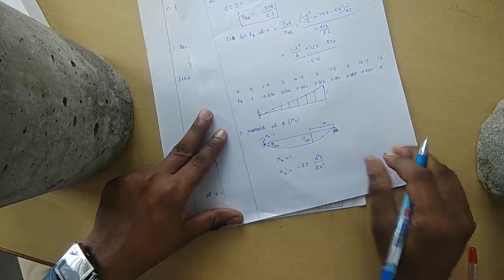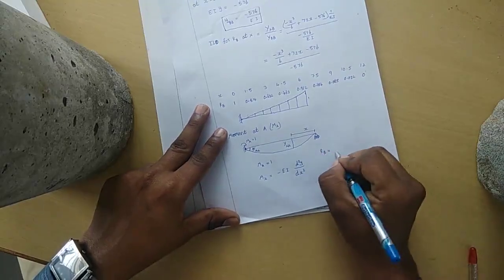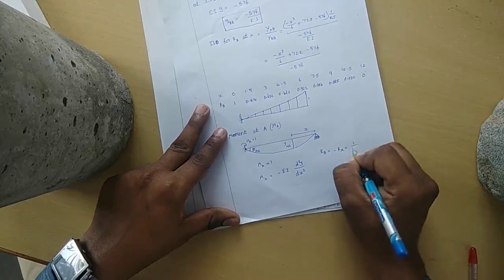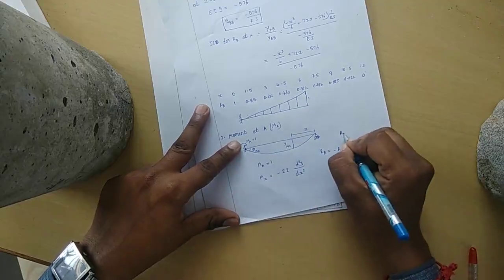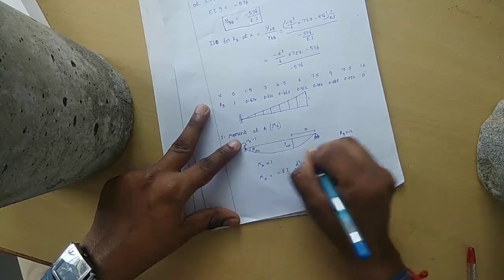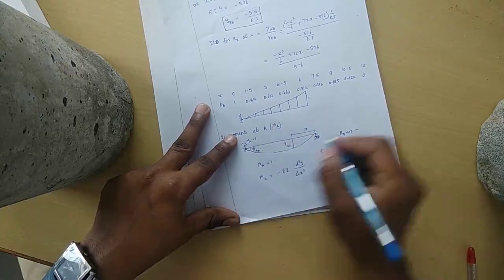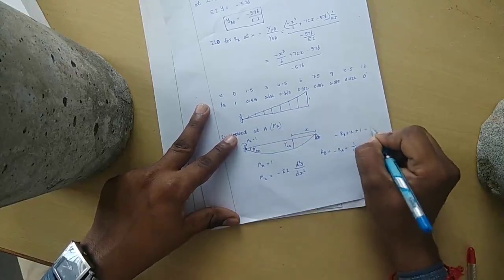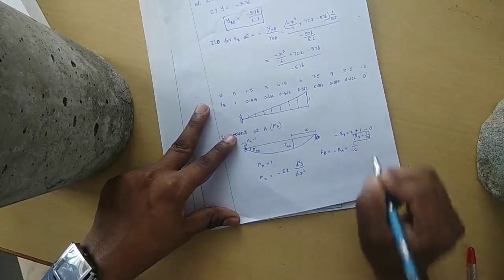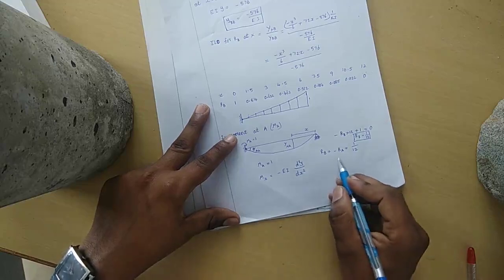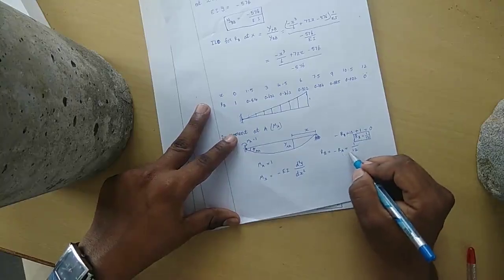This is the formula. If you want to calculate the reaction, that is RB, we can say that the value will be minus RA, equal to 1 by 12. If you take the moment about this point, then RB into 12 plus 1, because RB will be in anticlockwise direction, so RB into 12 minus, plus 1 equal to 0. So we can say that RB equal to 1 by 12. We know that RA plus RB should be equal to 1. There is no load acting on this point. So RB is positive means RA needs to be negative. That is only mentioned here.